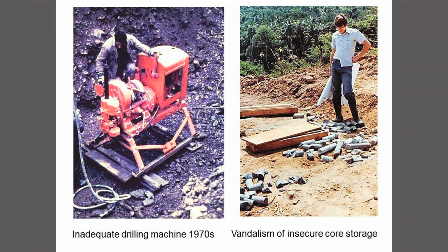There was no real method for storing the core securely, and you see on the right there a core in Sri Lanka on a dam project which had been vandalized and is of very little use for gathering information. Fortunately, over the years, due to a lot of pressure from clients and consultants, the drilling industry improved enormously. And today you can demand core in almost any location and expect and receive almost 100% core recovery. So that problem has been largely overcome.